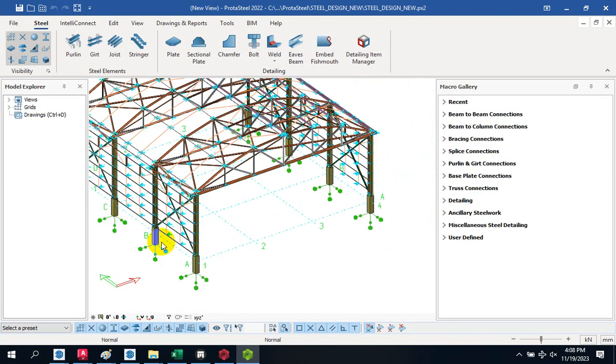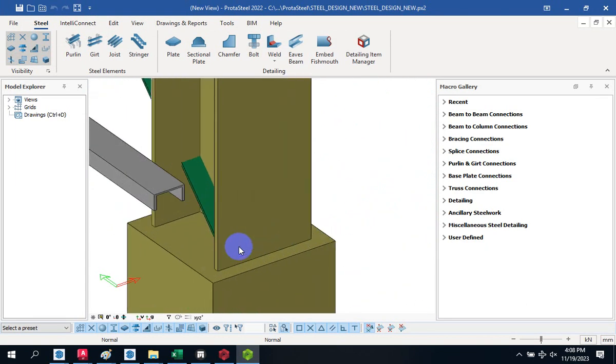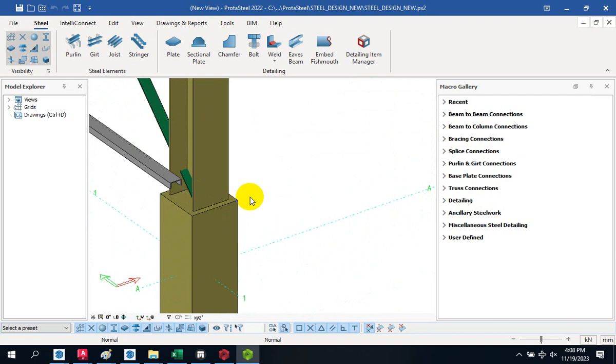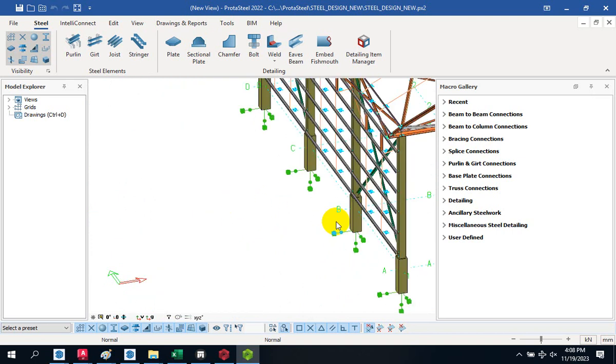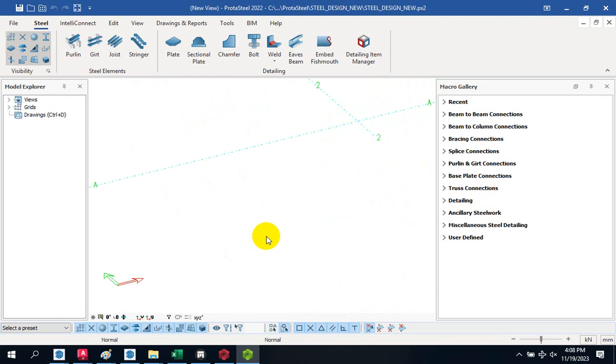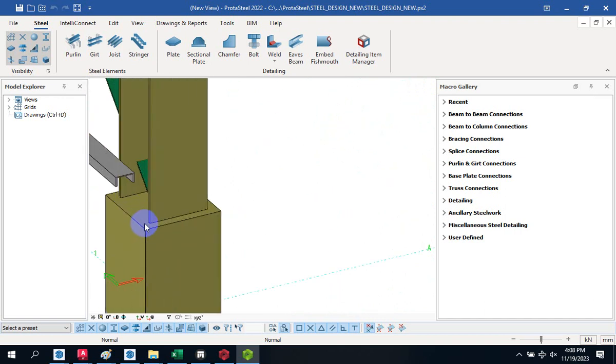So that's why. To create a base plate, the base plate sits on top of the concrete, and the steel will be on top of it. Then we will use anchor bolts. We will create an opening on the plate and then put the anchor bolt. We are going to demonstrate it here and right now. We have to pay very close attention to this part because this place is tricky.